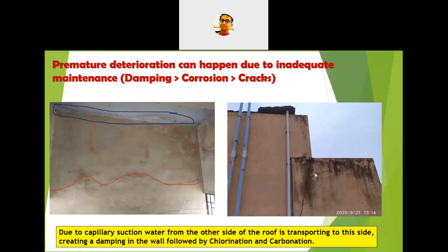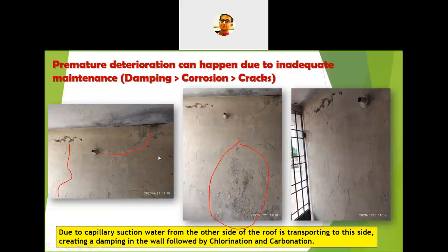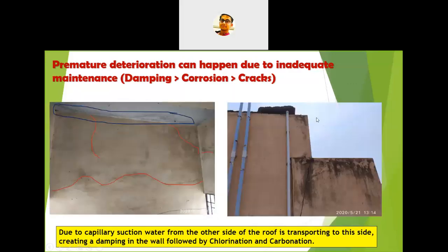So you can see here that this is the water tank, and this is a place that has been given just for inspection purposes only, but there is no proper drainage given in this particular place. I am showing you again, there is no drainage given in this particular place. So what happens is that due to rainfall and all, water gets accumulated in this place for 2, 3 days, and unfortunately this particular place doesn't get that much sunlight, so the water does not evaporate. So slowly, years and years after, the water was ingressing through this concrete system,